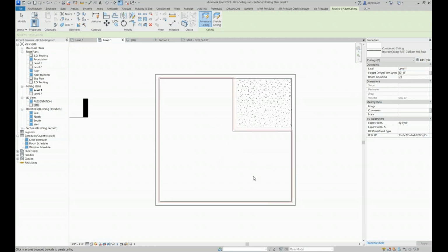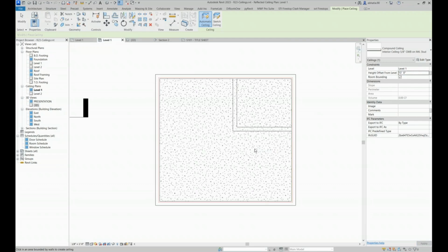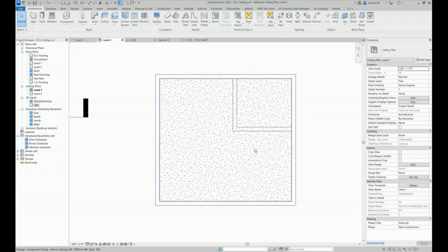So basically, if I draw a ceiling at 10-foot height, I'll drop that there, and you'll see that it draws it in that location. But maybe for this entire area, this could be like a warehouse situation where in the warehouse, you might have a ceiling that's actually much higher. And then just for the office areas, you might have a ceiling that's much lower. So your light fixtures and all that fun stuff can be placed inside your ACT or acoustic tile ceiling, and so on and so forth. So maybe you have a condition like this where you have a 13-foot ceiling, which actually covers the entire building, but then you also have your ceiling that is inside the office area. Maybe the 13-foot could be 18 feet or something like that. But this is just an example.